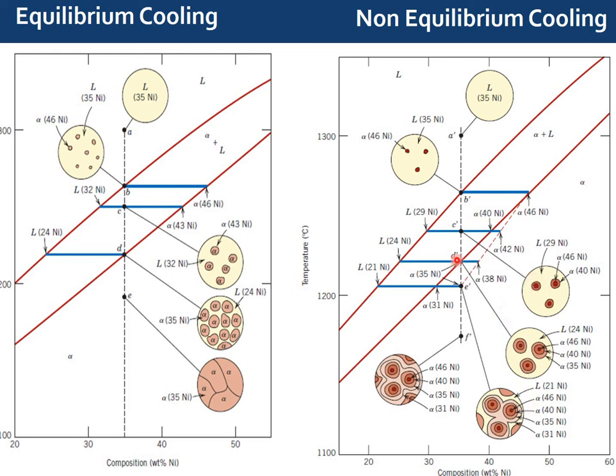So at D, you can see there is coring being observed, because when the inner part is not completely solidified, on top of that, there is a liquid layer being formed, which resists the heat diffusing out from the inner part.